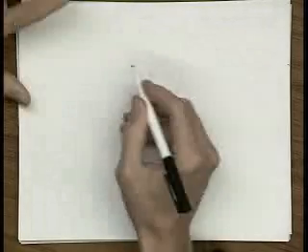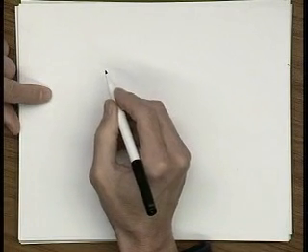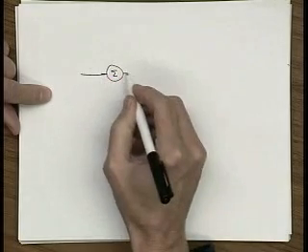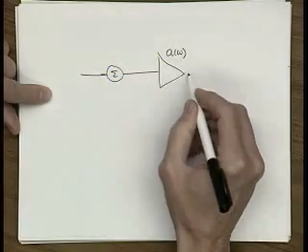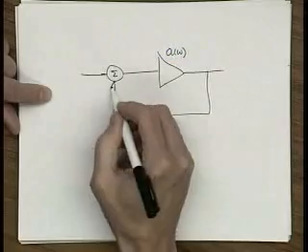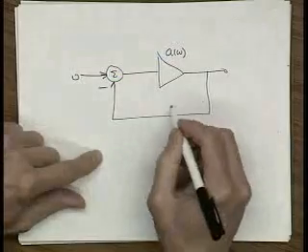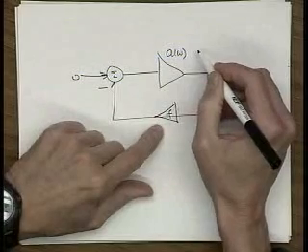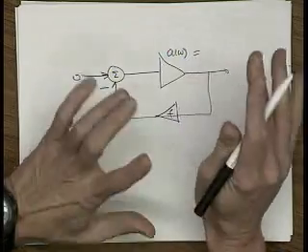If you remember back earlier in the year, a few weeks ago, when we did the bandwidth of a closed loop amplifier with feedback. Okay, remember I did this case? I said, let's make it just sort of generic here. This is A of omega. We feed it back, so it's this circuit right here. Let's make this F. Let's say A of omega is characterized by one pole. So this works for a one-pole response.